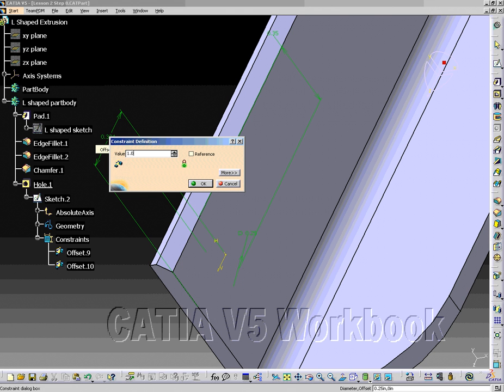The hole limits will need to be selected next. The limit will specify how deep the hole will go. CATIA V5 has several different options available for the hole limits. To specify a limit type, select the Extension tab located next to the Type tab. The first box in the Extension tab is an Options box. By selecting the down arrow at the right side of the box, you will see the different options you have to choose from. For this step, select the Up to Last option.